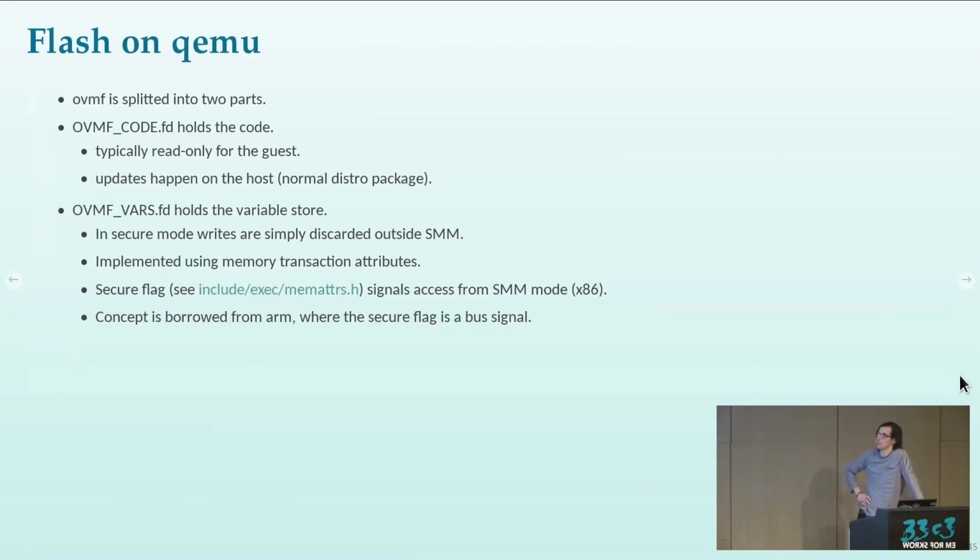It's implemented using memory transaction attributes, where, among other things, it is noted whether the secure flag is set or not set, and then the flash code can just decide, okay, we can allow this write or we can't. So that's a lot easier than on physical hardware.